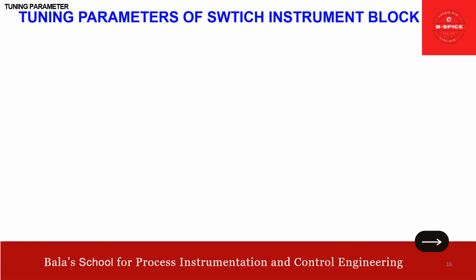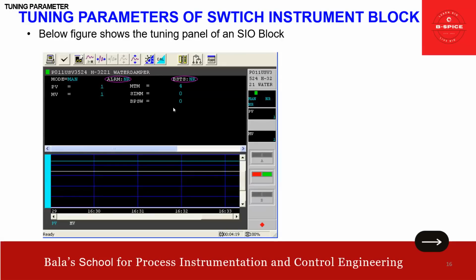Tuning parameters of a PID block. Sorry, not PID block, PID block we already covered. This is the switch instrument block. As I highlighted earlier, switch instruments are used to start, stop, monitor, and manipulate the status of various types of instruments. In fact, we have an enhanced switch instrument block also, but that is used for connecting to the FF faceplate blocks, Foundation Fieldbus. So this is the look and feel of the SIO block. You can see here the mode, the PV, the MV, the alarm status, the simulation, the bypass switch, all these are there.